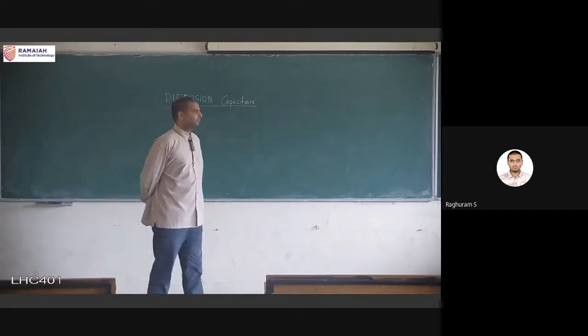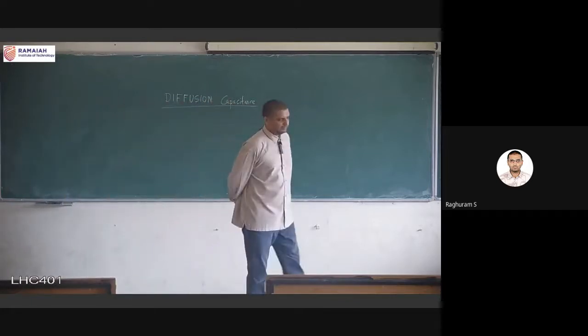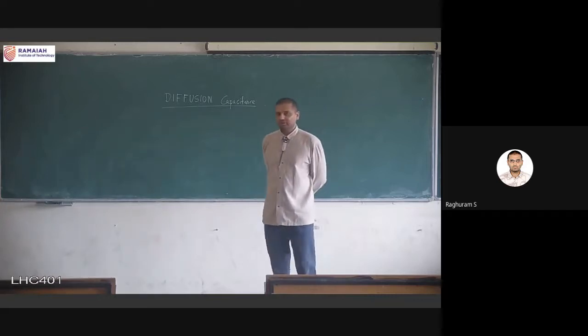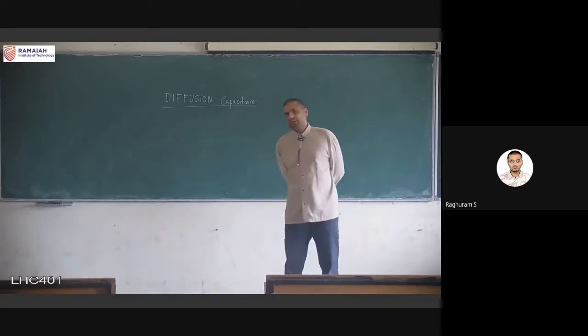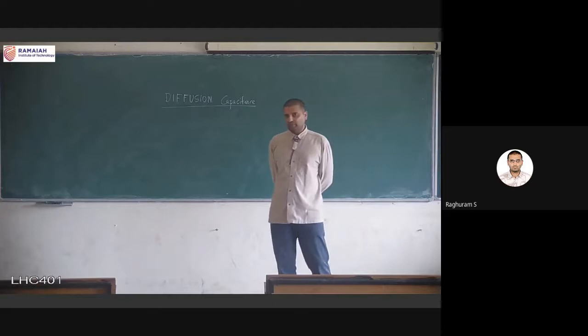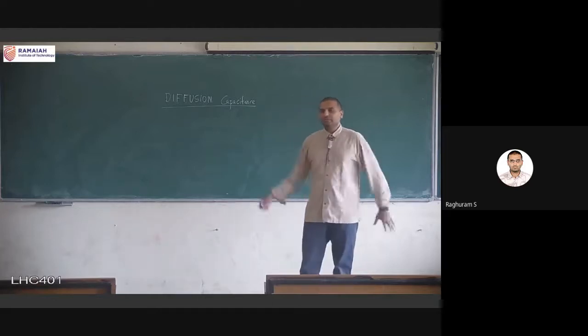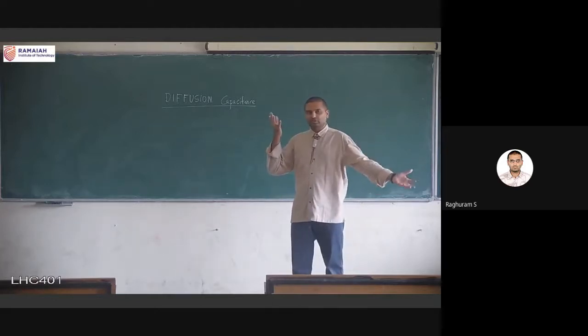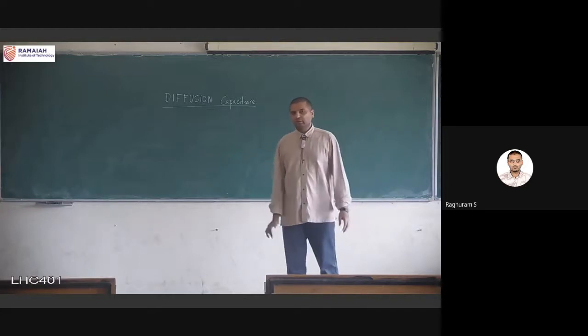So the first component was called gate capacitance. Cg was coming in all of the expressions, all of the terms. This time we are talking about the diffusion capacitance. There are two diffusion regions. The source is also a diffusion region. The drain is also a diffusion region.